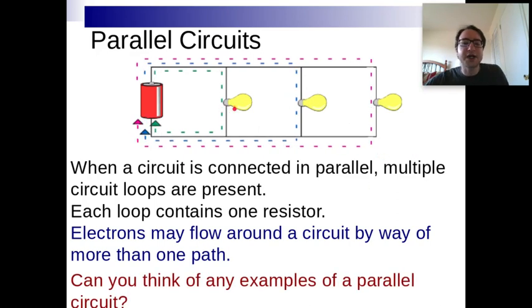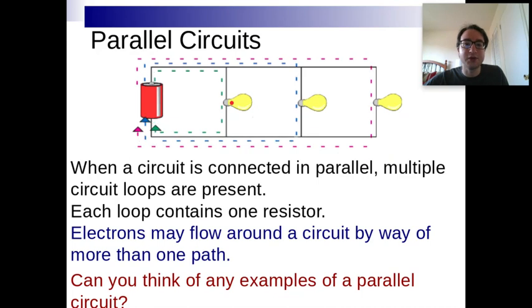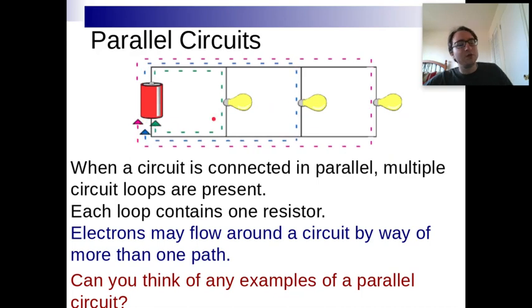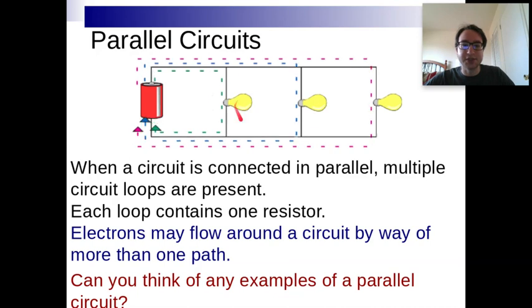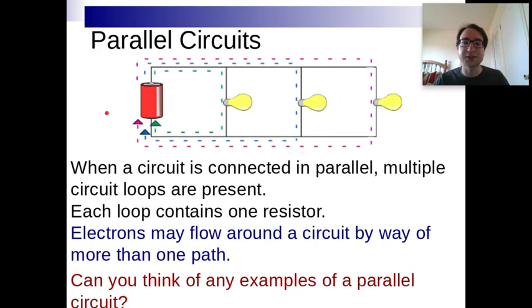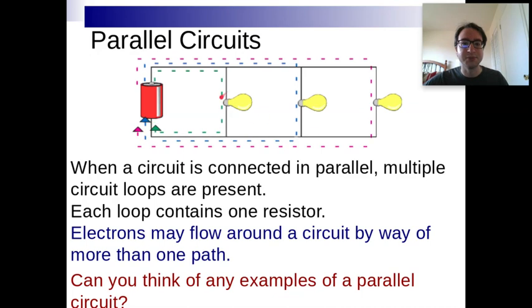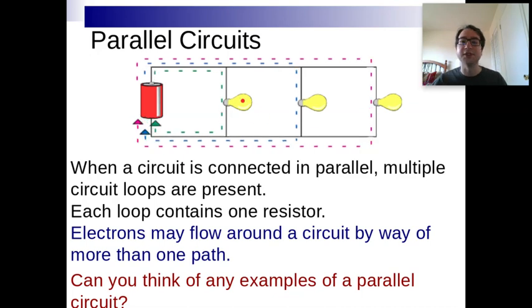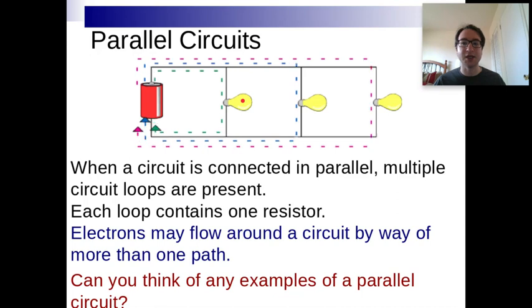So another factor of a parallel circuit is that if we were to pull one of these light bulbs out, well, okay, that would kill this branch, say, if we turn this light off. Well, that's okay, though, as far as these other 2 go. They still have their own connection to the battery. It's a big advantage of a parallel circuit over a series circuit, that if one part of a parallel circuit burns out, well, the others aren't going to die off because they have their own line of current feeding into them. Not so in a series circuit. As you know, you pull a component out of series, you've now made an open circuit and nothing receives any current.